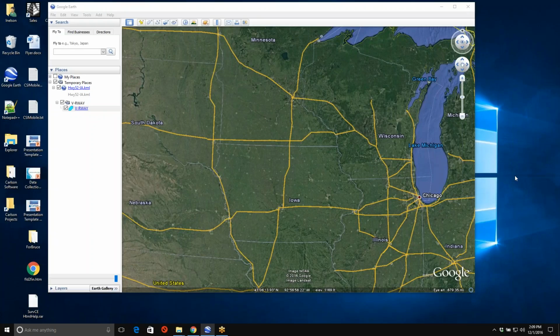In this video recording, we're going to demonstrate some steps that you can take to convert freely available LIDAR data from, for example, in this case, a UTM 15 north metric coordinate system into a regional coordinate system for use with existing ground data found in ditches and forest slopes and back slopes of roads, to then be coupled with RTK GPS data for edge of pavements and shoulders that will have more precise survey elevations on them.